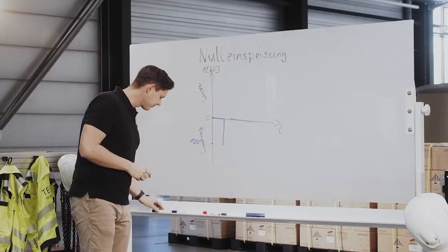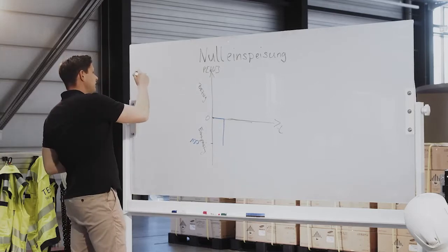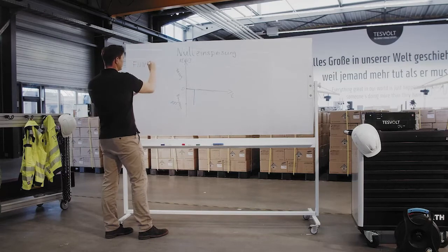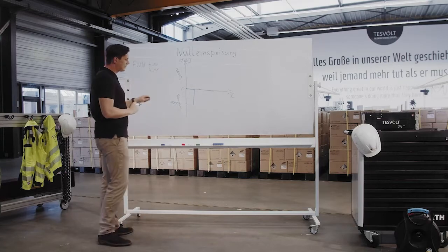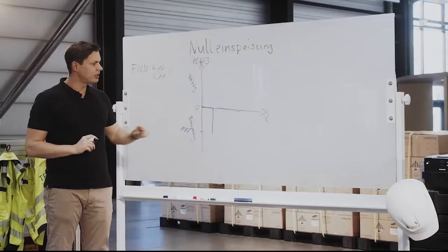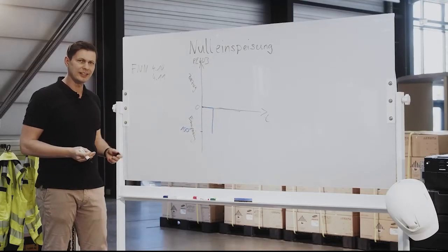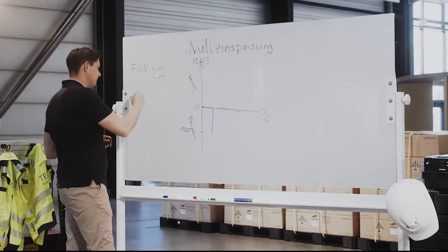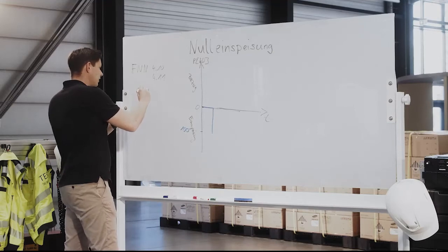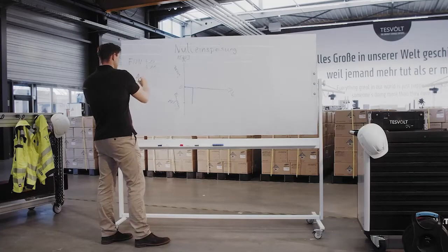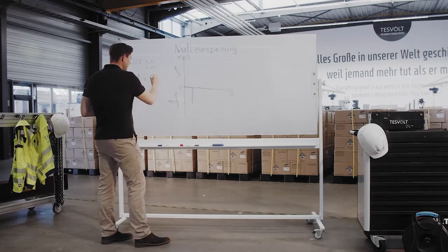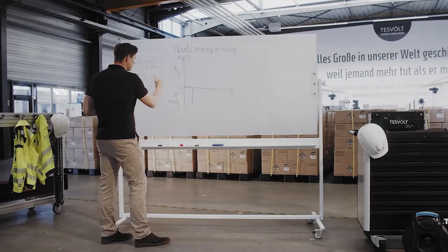The standard of the FNN application guidelines 4.10 and 4.11 now prescribe that I must adjust this load variation in the zero feed-in within a predefined period of time. Otherwise, it does not meet the requirements of zero feed-in. The standard states that a total of 90% of the feed-in must be balanced in 3 seconds time.